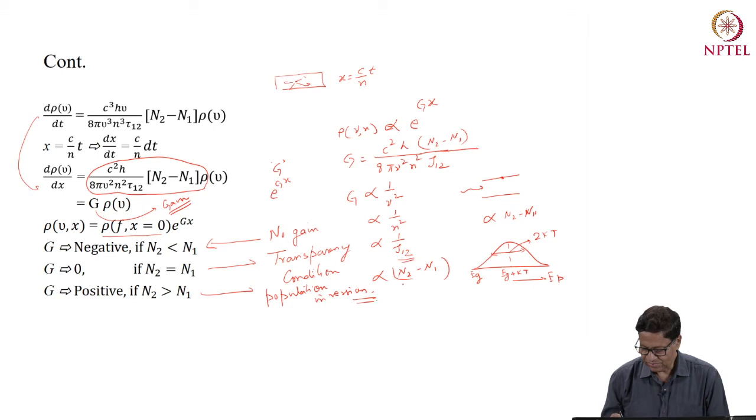Whereas in case of a laser diode, if I plot the same curve, E_PH, because the G is riding on the exponential and the power is increasing at an exponential rate, the same curve will become very narrow. This is the spectral width of the laser diode because of the whole stimulated emission process.